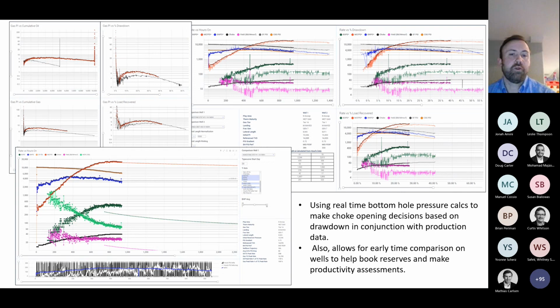Like I mentioned, we have reports coming in starting at 5 in the morning or 6 in the morning, and then every 6 hours after that, we have reports coming in on these new wells that are coming online. As soon as that flowback data comes in, it's immediately uploaded into Whitson, and then bottomhole pressures are calculated, and it's turned around quickly, so we can quickly get back to work, and we don't have to waste any time uploading that hourly flowback data.